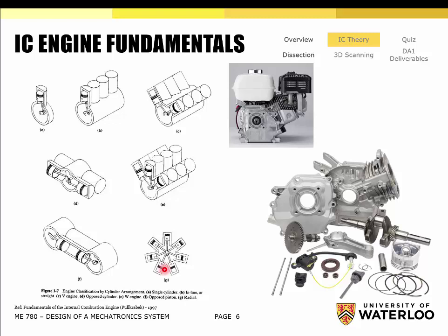It has the weight balance benefit, but also you're kind of unshrouding all of the cylinders to get direct access with the incoming airflow. Okay, and that allows them to cool a lot better, especially when you're operating at very high altitudes where the density of the air is very low. Once again, this is more detail than you all need to know, but it's good that everyone had their own idea of why it's the case.